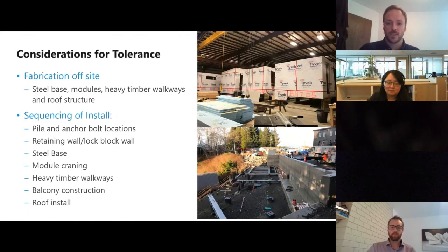So every single mod we would set, we would then bring the surveyor in. We took 4 points on each mod at each point, and then in between each mod there's a squash pad, and that is typically a 2x6 or 2 2x6s, and in this case I believe it was 2, and we would vary that elevation based on what the elevation was once we set it. And so it worked out perfectly, but it was a little bit nerve-wracking when it's all theory and you're trying to put it all together. James, next one, please.